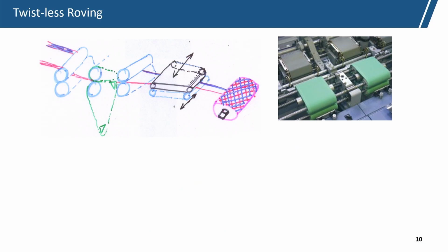And apart from this, there are other methods available. So, in the worsted spinning, we give the roving twist not by the flyer. This is the flyer-less roving. It is only by rubbing action. Here two felt drag aprons are there. They move in the longitudinal direction just to feed the material.